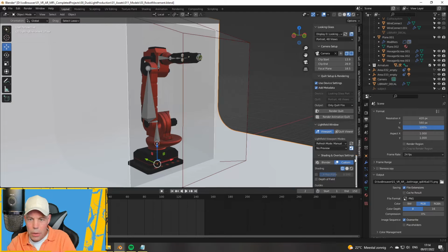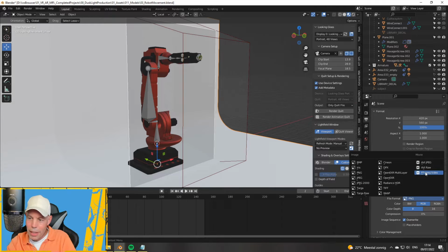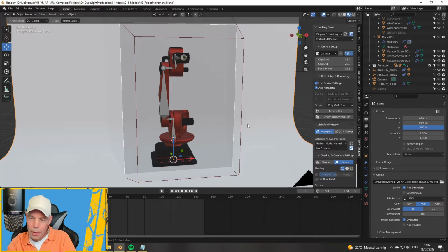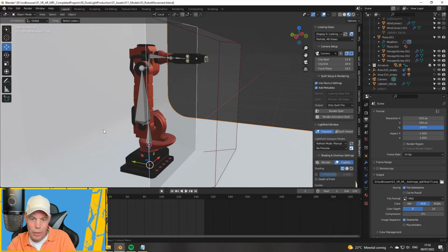Another thing which is recommended is when you go over to the Blender tab on the output properties, at the output section, you can select directly the MPEG files and the movie files. I recommend to use PNG, save them as individual images and later combine them into one animation. And the reason is if something happens during the render, you will lose all the work in progress. But with the PNGs, every PNG rendered out is saved on your hard drive and that's still there. And then you can start from that point on to finish the complete render.